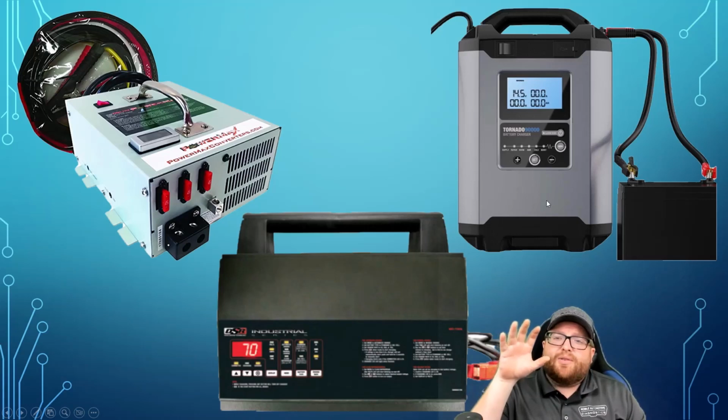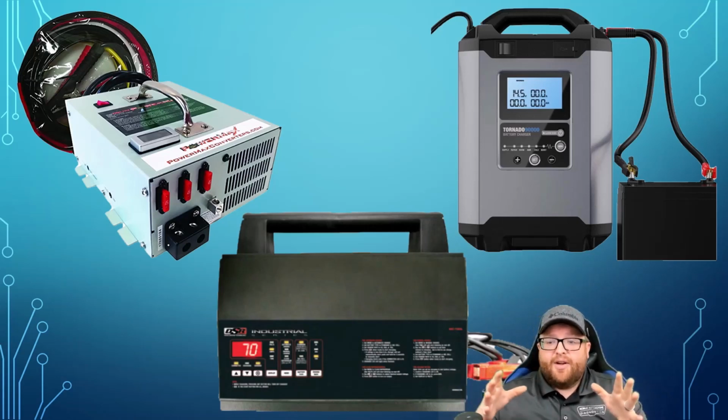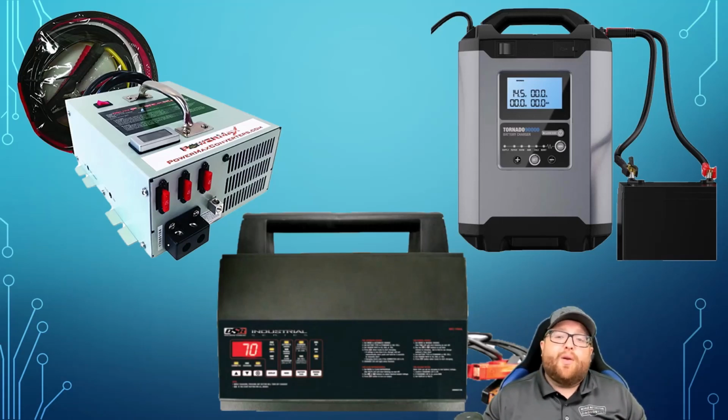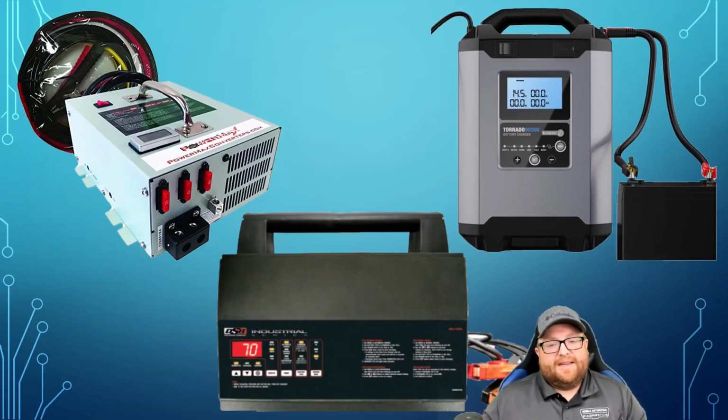But that's who's actually building that for them. So the reason you have this, though, is it keeps it at a certain voltage, and it keeps the voltage up. So when you have a high demand of current, it doesn't bring your voltage down. Now, the old roll-around battery maintainers, chargers, or whatever you want to call them, those actually work in a different way. They actually put out more voltage than they do amperage. And even if you put it on a high amp mode, like engine start, it's not going to work out, because you're going to have something called AC ripple in there, and it's going to start to cause issues.